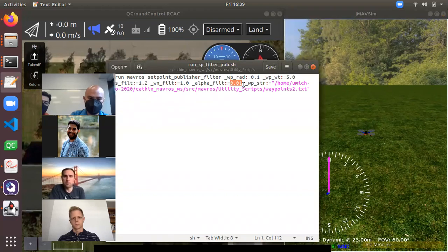This is really the planning part of the problem, not the control part. This is issuing the trajectory which the controller is going to follow. We are essentially saying that our controller is going to do well, but only if the trajectories are reasonable. And for this value of alpha, based on numerical observation, the planned trajectory is going to be nice enough that the response is going to be good.